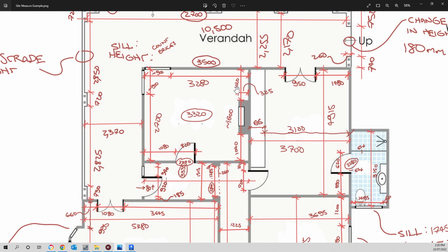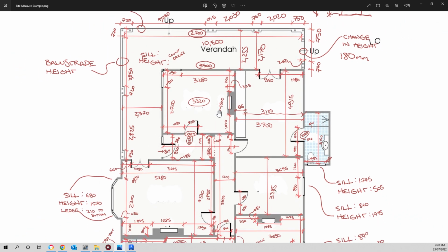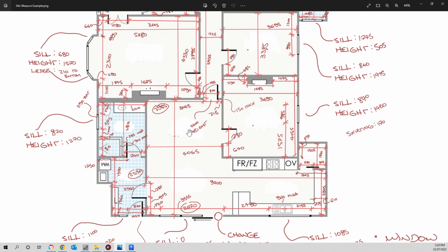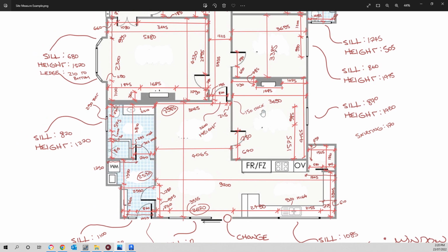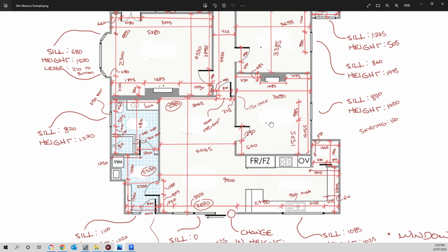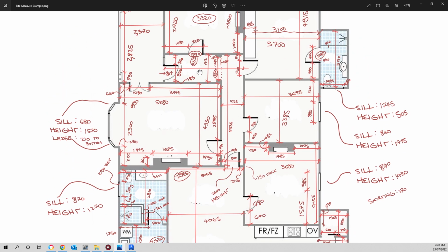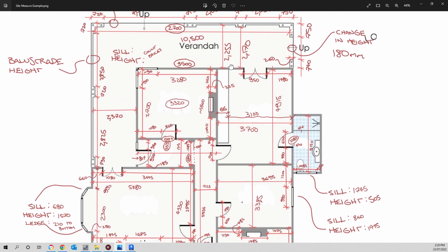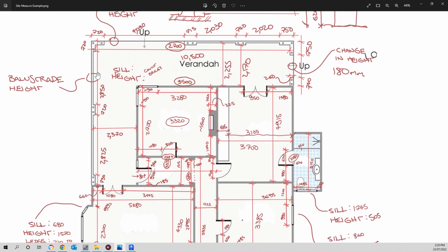These dimension lines indicate between which surfaces we're measuring, and then the number is obviously the distance in millimeters. You will be able to do that in your own homes using a laser measurer or a tape measure. Just go through your own houses and take these measurements so that you will be able to recreate this plan in Revit afterwards.